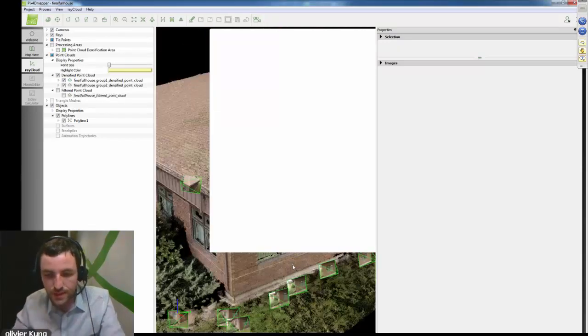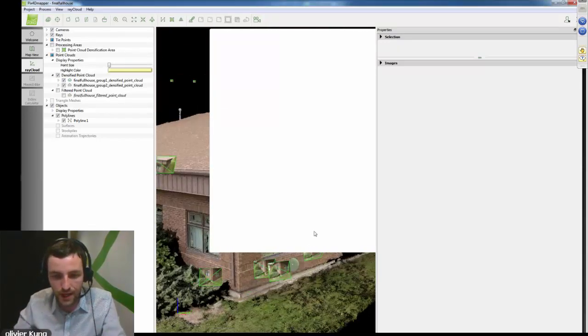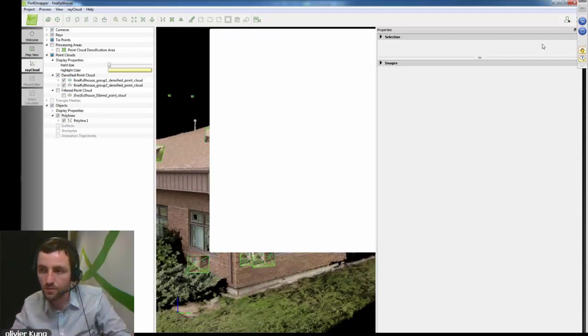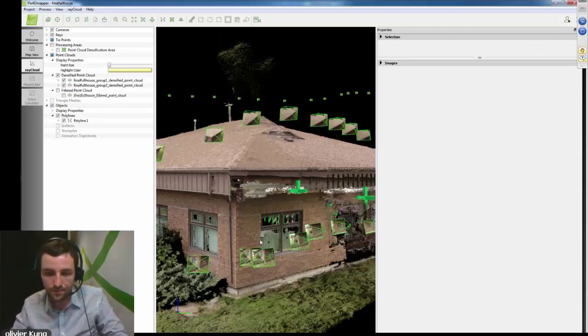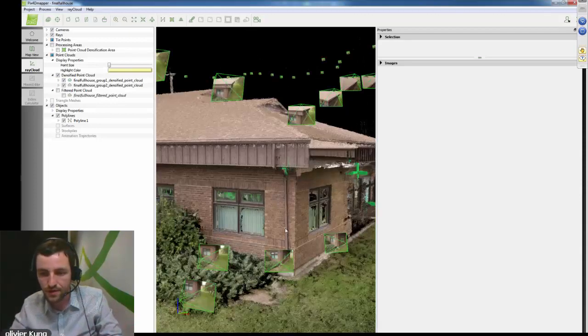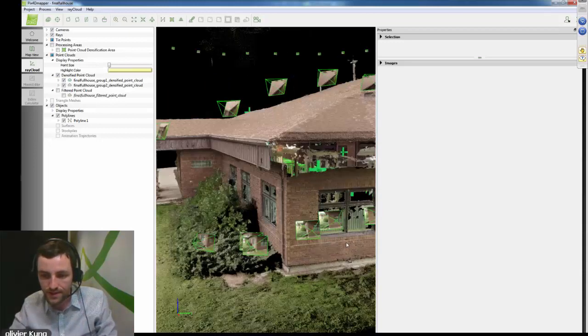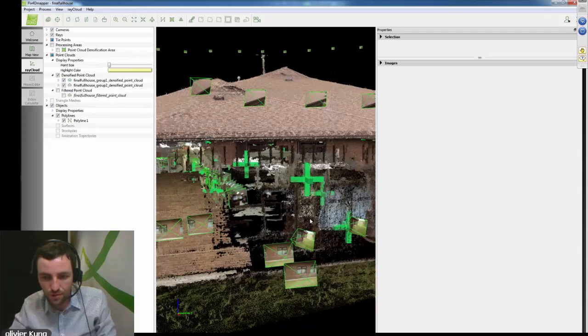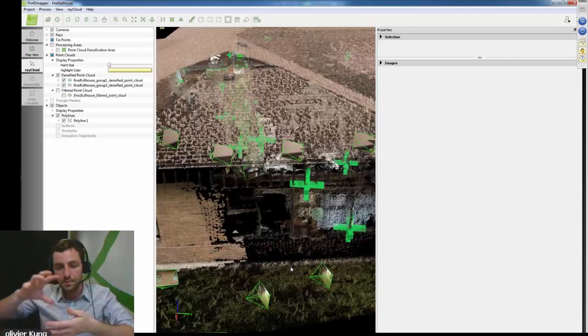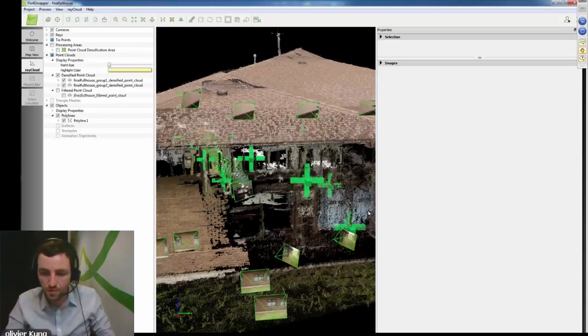So in that case, what we did is that when we had to go closer, we started to take even more pictures to make sure that the overlap would still be sufficient in that area. And as you can see, just at this angle, the density of points is lower because of the trees. We stopped taking pictures at that spot and started moving in different directions.